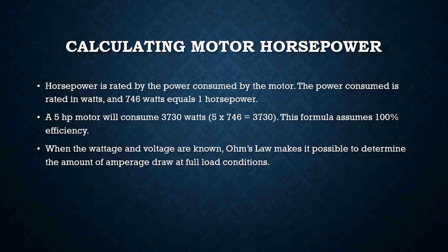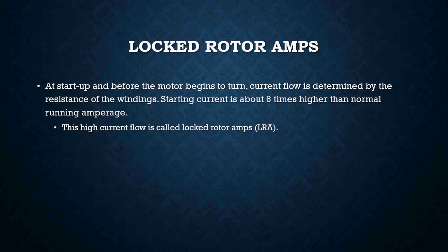So we sometimes have to calculate stuff to see whether or not a motor is operating within the correct ranges that it's rated for. So when the wattage and voltages are known, Ohm's law makes it possible to determine the amount of amperage draw at your full load conditions.